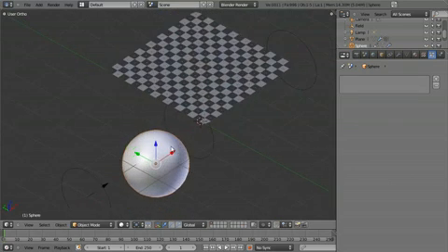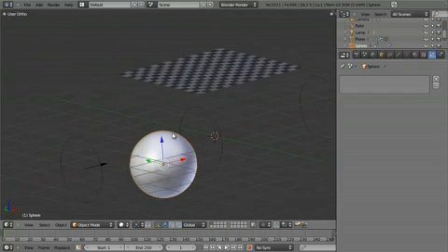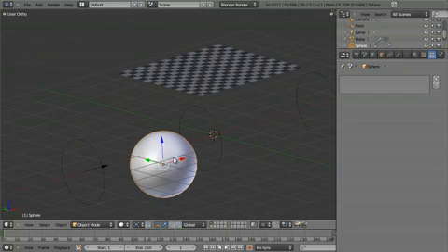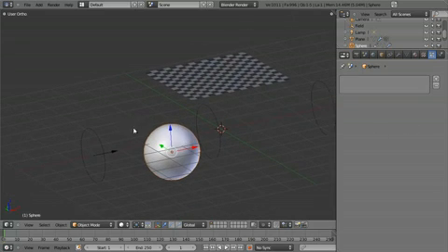In order to get good, fast simulation, something that you generally will do, at least when you have a full scene, is create very, very simple collision objects, such that you have just rough indications of a shape. So if you have a person, you would have just a very low poly cage mesh that acts as your collision object that is not rendered at render time, so that it's basically just blocking that one thing. And this is what really allows you to optimize your simulation to save some time.